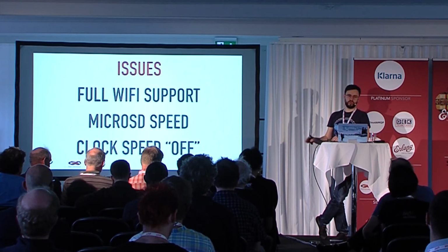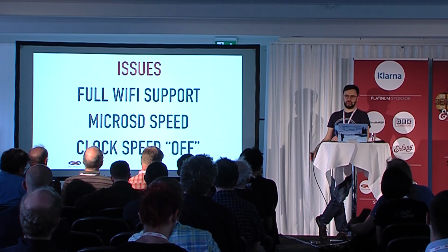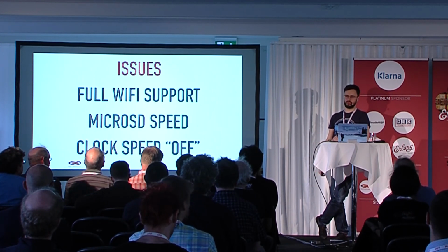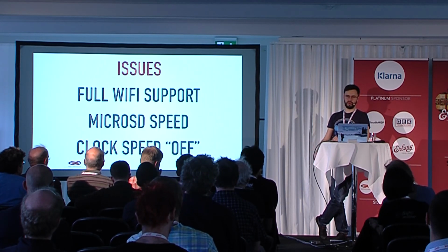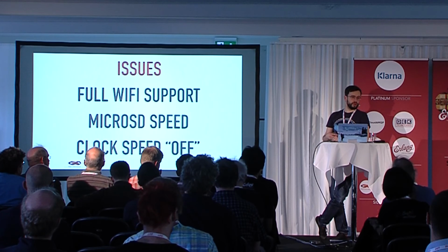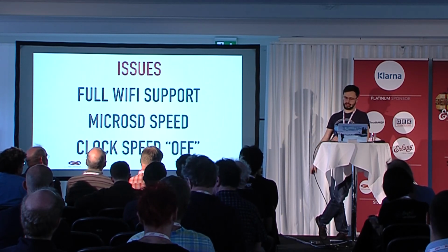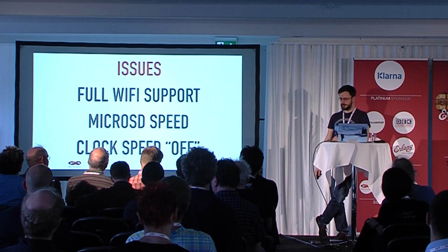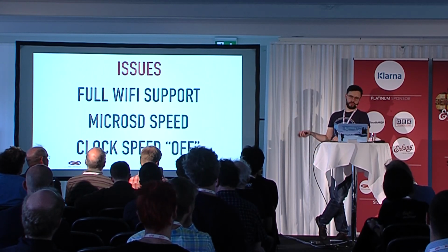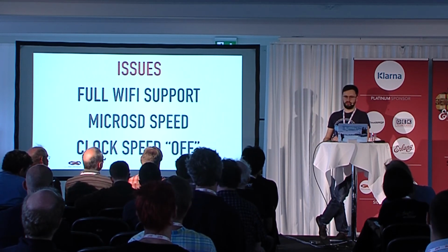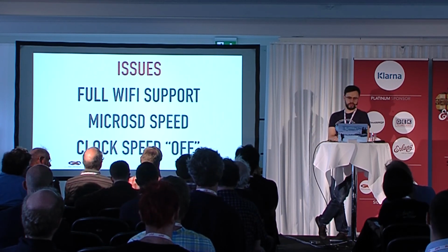But for example, if you boot the board with the BEAM with the Wi-Fi enabled, you will connect to the first open Wi-Fi that exists and get an IP number, and then you can actually ping the GRiSP. Once this all works, you'll be able to connect distributed Erlang to it, or even access the serial console over Wi-Fi, things like this. So this will be really cool. As I mentioned before, we're also working on getting the MicroSD speeds up, because we're not using DMA yet, and we just have to do it. So it's on our to-do list.